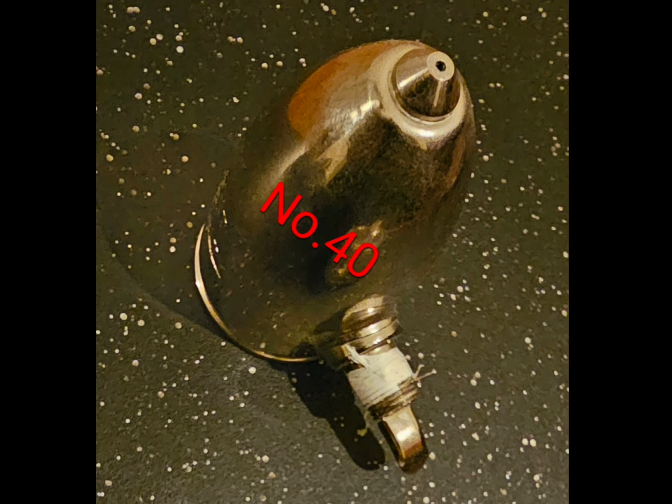Now, lobby radiators that are 15 sections or longer, the average size that I had in those buildings was either 1 inch to 1.25 inches, and that was what was inside of the apartments. You go into the lobby radiators, you have much larger openings. The service valves were 1.5 inches, big old monsters. And you would figure, okay, if this theory were true, this opening here being larger should be enough to generate enough wind capacity to push the piston and cause it to stay in the closed position.